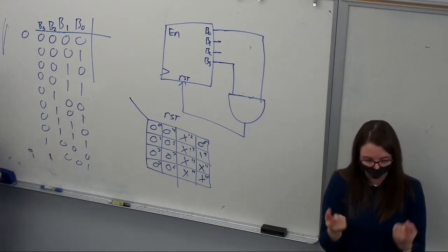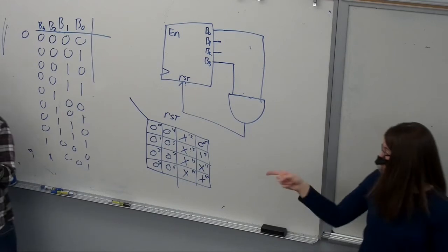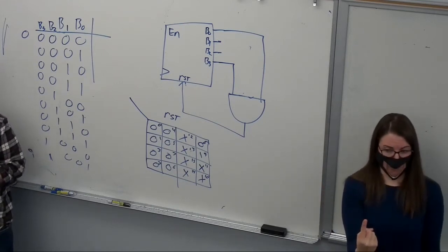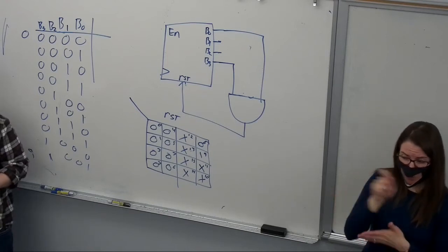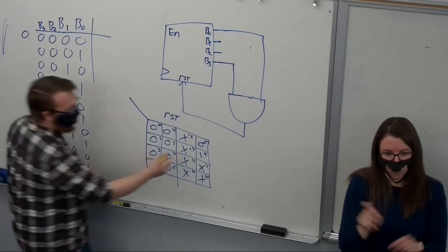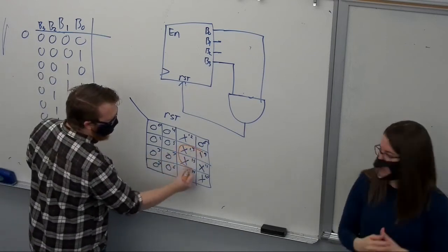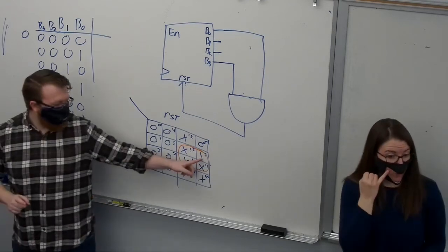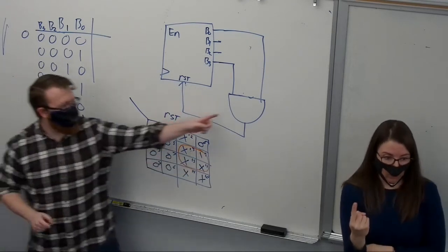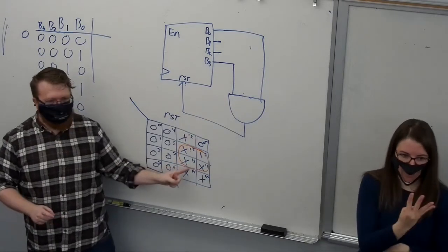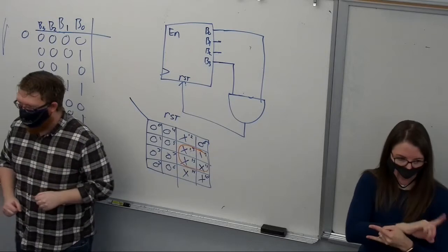So what do? Well, this K-map, I only have 1, 1. Yeah, exactly. So what do I want to circle? Just the one, or you could circle also the don't care, so you can do like 4. Yeah, exactly. I can do the square of don't cares. So if I did just the 1, that's not the simplest term. That would give me the 4-input AND gate. By having these don't cares around it, I get a 2-input AND gate.